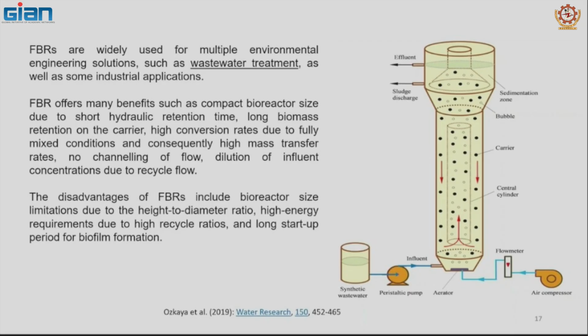But there are certain disadvantages also with the fluidized bed reactor. It is the size limitation due to height to diameter ratio; the height requirement is much more than that of the diameter. High energy requirement due to high recycle ratio and a long startup period for biofilm formation. Only those operational constraints are there. In an oxidation pond, nothing is there, it is open. You just allow the wastewater to enter the pond, just seed it, nothing to do, it is automatic. It takes months of time, but degradation is there.